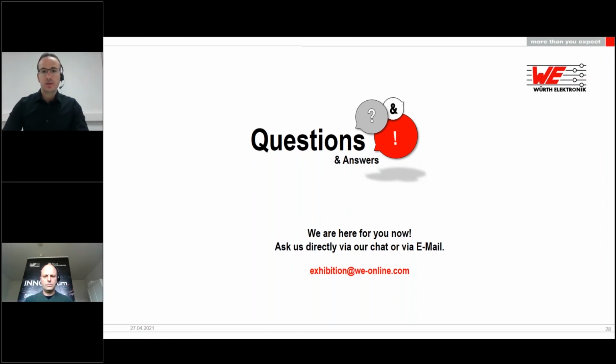Yeah, I can answer that question. At the moment, we don't have a transformer which is optimized for these output voltage levels, I mean, a reference design with a flyback topology like this one. However, we have received this request already in the last months, two or three requests already regarding high voltage GaN devices. So we are working on a reference design optimized for these output voltage levels. The final might be 6 volt, -3 volts that we design at the end, but it's still not decided.